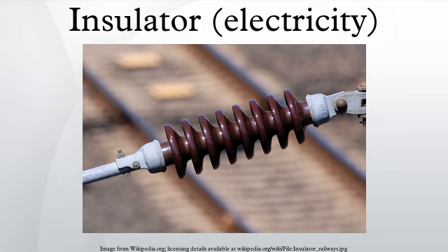Shackle insulator. In early days, the shackle insulators were used as strain insulators. But nowadays, they are frequently used for low-voltage distribution lines. Such insulators can be used either in a horizontal position or in a vertical position. They can be directly fixed to the pole with a bolt or to the cross-arm.